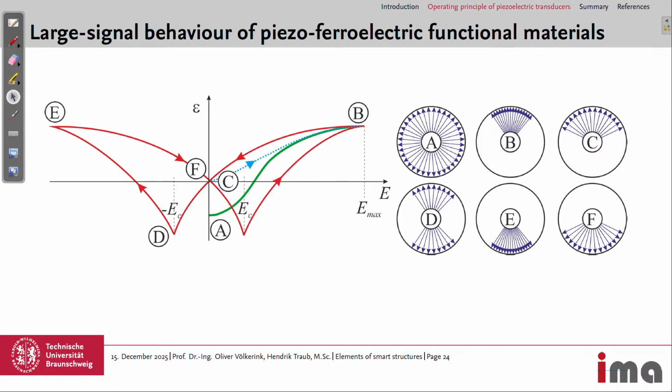You can use the d33 effect, in which the effect aligns with the direction of the field, and you could also use the effect perpendicular to the field. So you could change the position of the electrodes. In all these cases, the change in area is very, very negligible, so we ignore it. This is what we assume, at least.